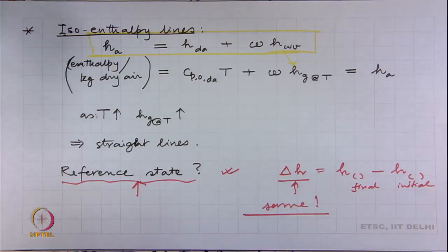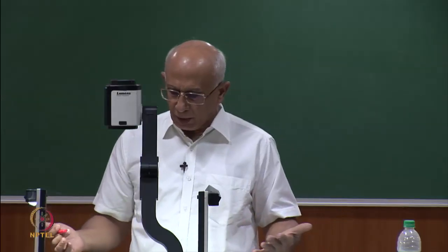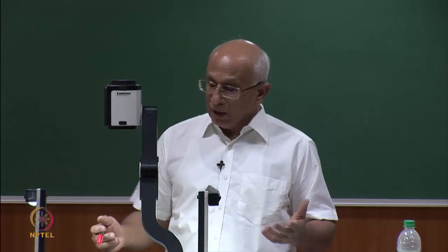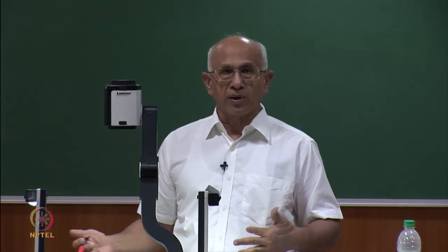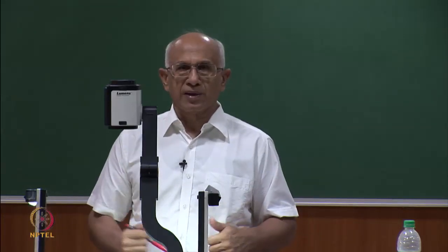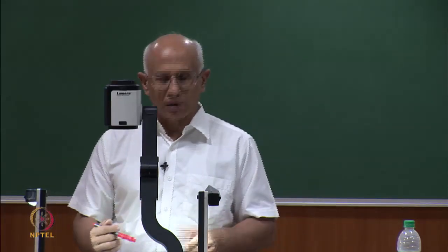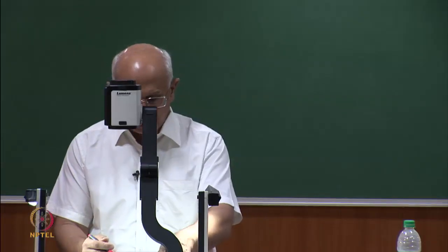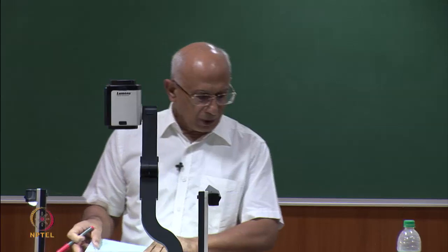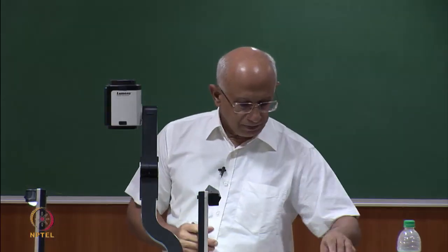So, to that extent we do not have to worry about what these are. If there are two people solving the same problem using two different charts where the reference states for enthalpy are different, the individual values they keep getting are different, but in the end all calculations where there is a difference of enthalpies coming in, those values will be identical. So, we do not need to worry too much about it at that point. That is what we have for specific enthalpy.